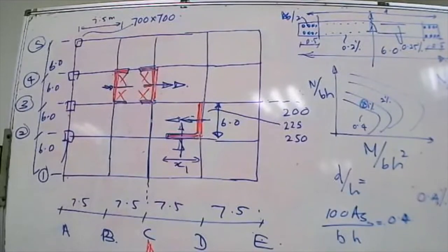And for those, we will do a 3D model on computer. And it is not a waste of time. It's a worthwhile exercise. But trying to do a 3D model for a 10-story building, knowing very well that the deflections are going to be so small, interactions are going to be so small, you'll be just wasting your time.